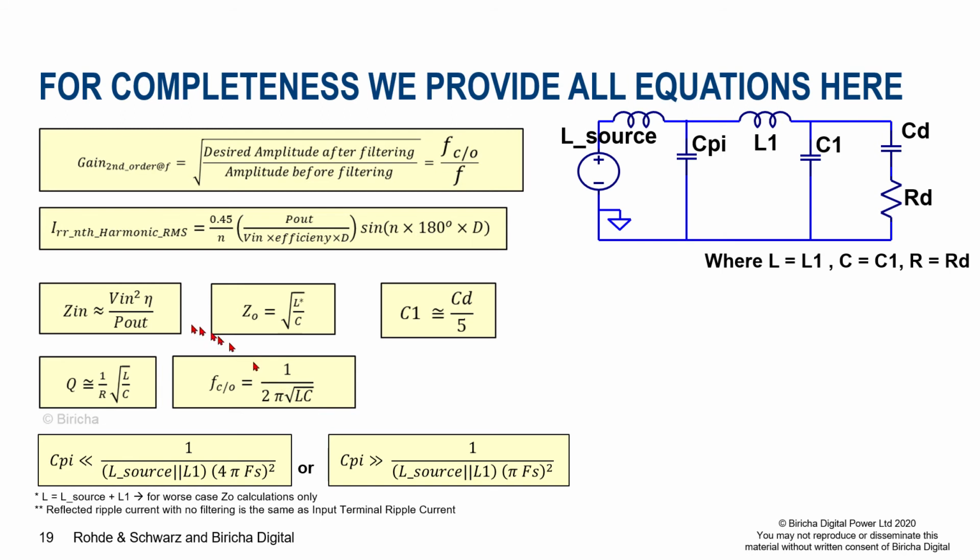In particular, for using the Middlebrook stability criteria, we were limited with the Z out of our filter, and we calculated all of these again. We drew it on the impedance paper, we drew the lines, we crossed the regions out, and we homed in on the values of L1 and C1, and of course the damping capacitor and damping resistor. And here's the equation for the damping capacitor. And to set the Q to 1, here is the equation for the damping resistor.